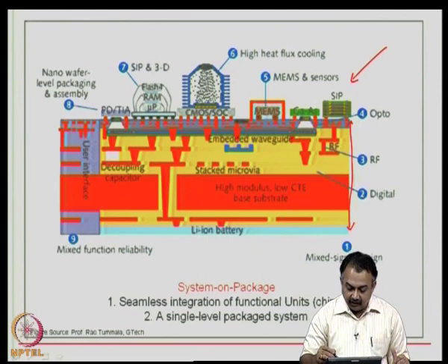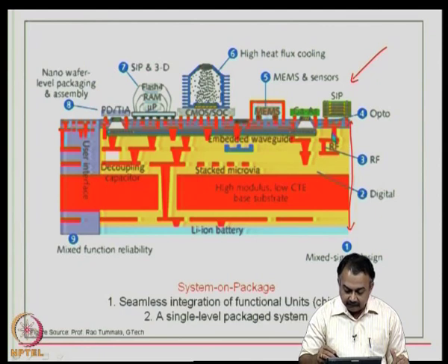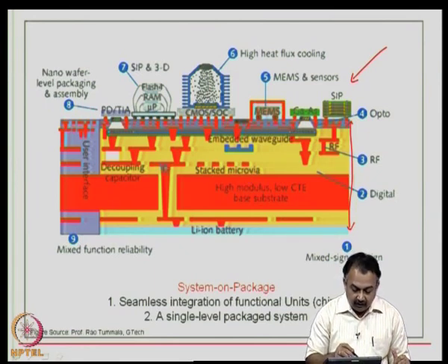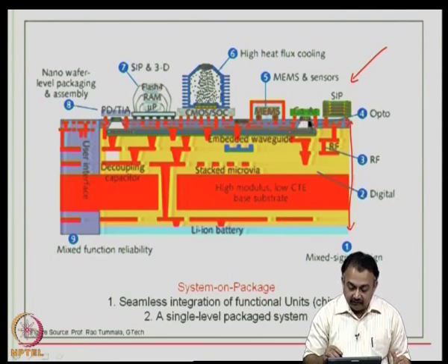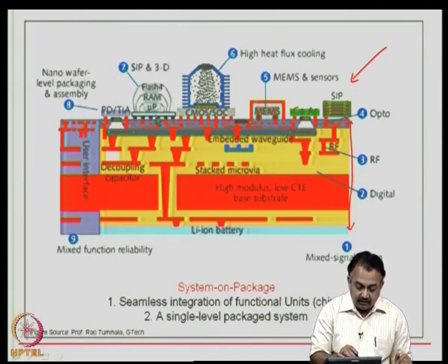You can have embedded RF components, then embedded waveguides, stacked microvia structures of the order of 50 micron, decoupling capacitors embedded again, and on the surface you can see active devices like system in package mounted on the SOP, gallium arsenide deposited thin film structures. You can also have embedded actives in this structure, MEMS, then CMOS system on a chip, then you can have 3D structures and so on.